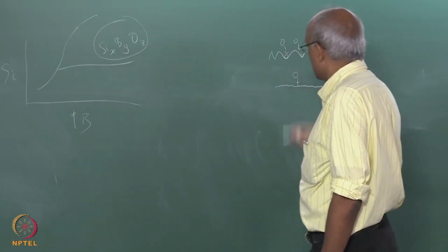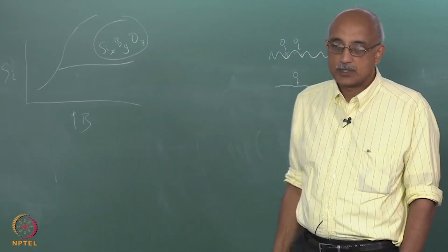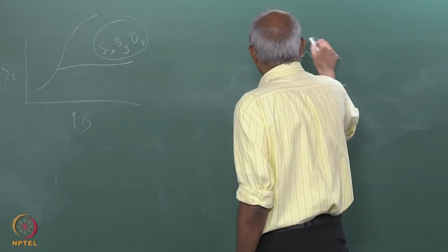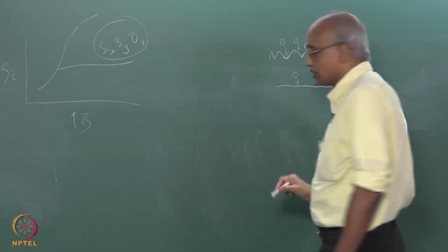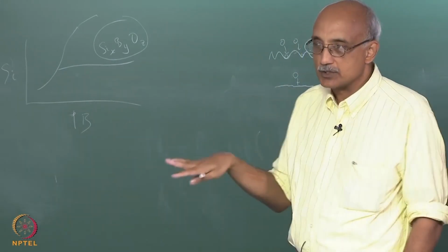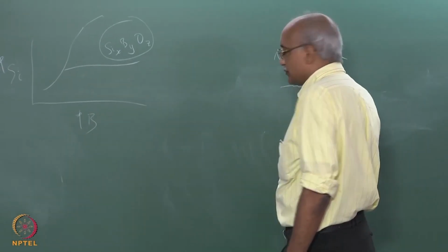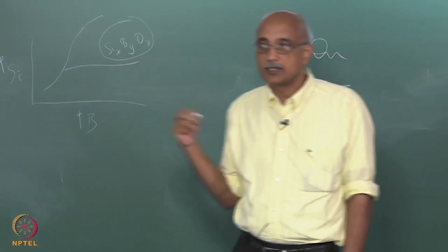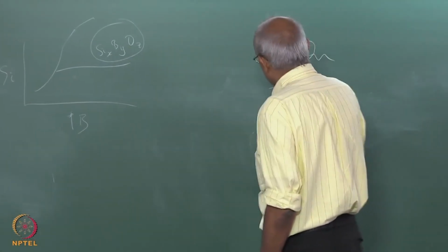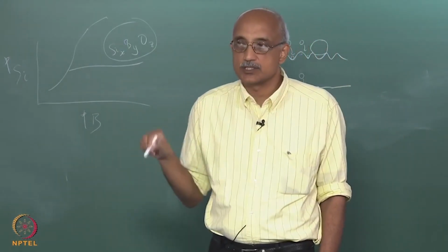On the other hand, if the arriving molecule is larger than the surface roughness, then as you can imagine, its contact is actually going to be reduced. It is going to be sitting on just 2 points instead of sitting on the entire surface. So, the implication is, as you make the surface smoother and smoother by adding dopants, the probability of capturing an arriving molecule actually decreases.